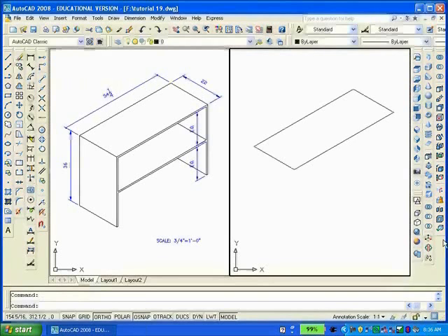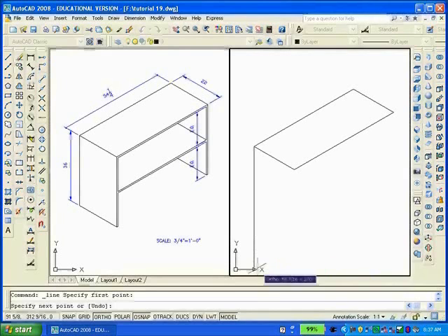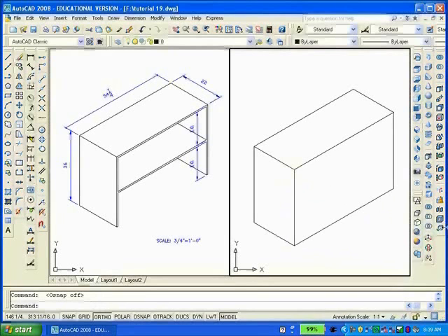To draw the left side of the bookcase, we have to toggle the F5 key. Now draw a line from the intersection 30 down to 36 units, toggle again, enter 22, and move the mouse up to connect to the other intersection. Now, starting on the right side, draw a line downward 36 units, move the mouse to the left and connect to the left side. And break this last line in the middle somewhere.